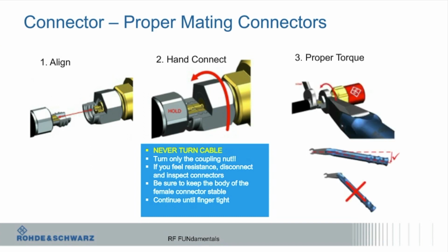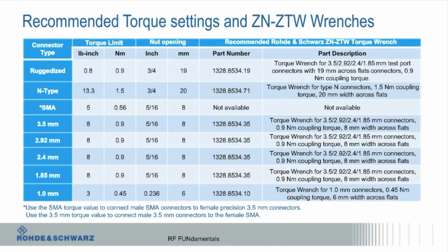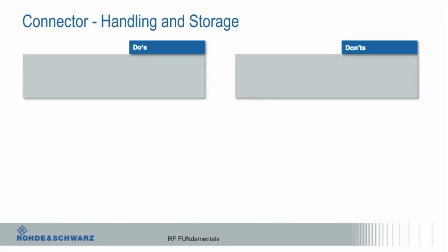And again, this is especially for VNA stuff. See, there's a Cal standard on there. So the Cal standards you'll even find, particularly if you get above probably 18 gig, if you don't torque them, you're not going to have a repeatable calibration. Okay, kind of beating this to death. Here's a bunch of different wrenches and what the torque is. I'm not going to quiz you on that because I don't even remember them.